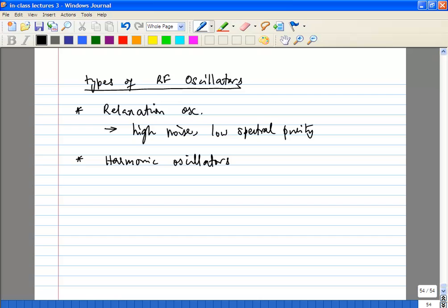These are the most popular oscillators used in RF transceivers. Now, if you have other applications like microprocessors or maybe even CDRs, you could make a case for ring oscillator based PLLs, but typically in RF circuits even ring oscillators are not very common, because the noise levels are too high.